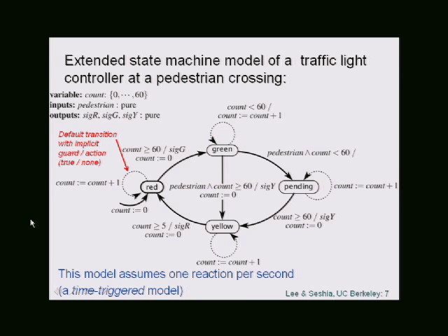So that was because we found that when we set stuff like exactly equals something. Okay. All right. So that's a good point. What Rafael said was that if you set a guard to test if a variable equals a value, then it's a very brittle condition. It might be that the variable equals the value, but if it's a sensor value, there could be a little bit of noise in the value. So you should be able to tolerate plus or minus some epsilon, right?